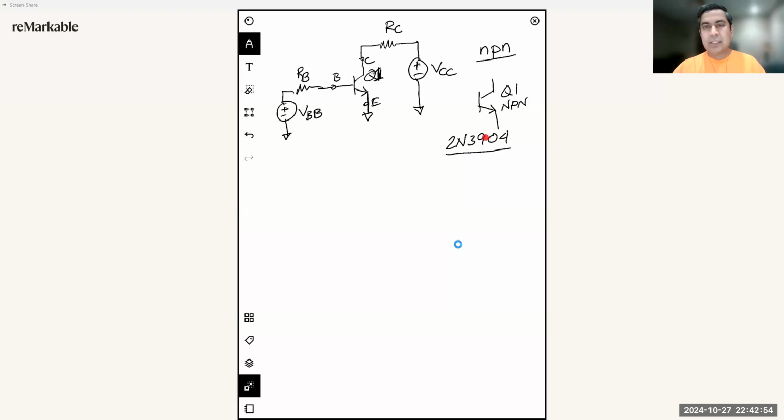The way to find it is to right click on the device and say add new device. The window that opens has the bipolar transistor Q1. You can select the pick new transistor button. Once you hit that, a new window will appear where you can see lots of models for these BJTs.